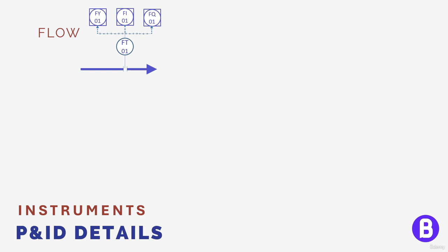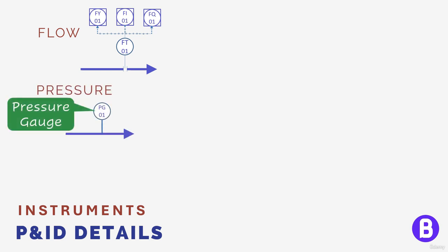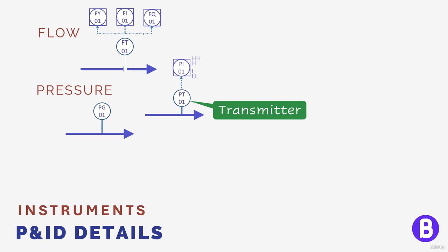So through instruments, we can also monitor the pressure, whether this is from the field based on a pressure gauge reading, or to send the reading to the DCS to be read from the control room with an alarm, so that when the pressure goes too high or too low, or even use it as a control parameter to set pressure to a predetermined value.